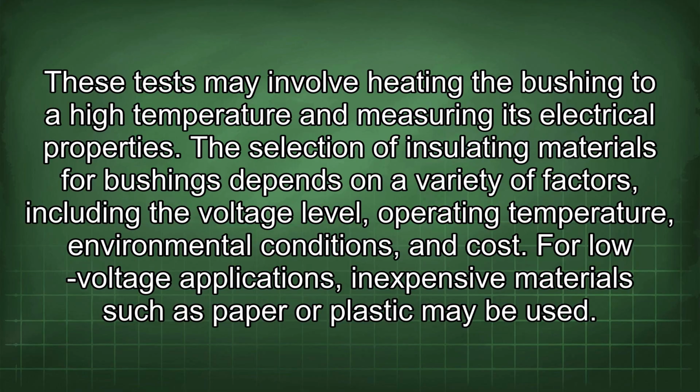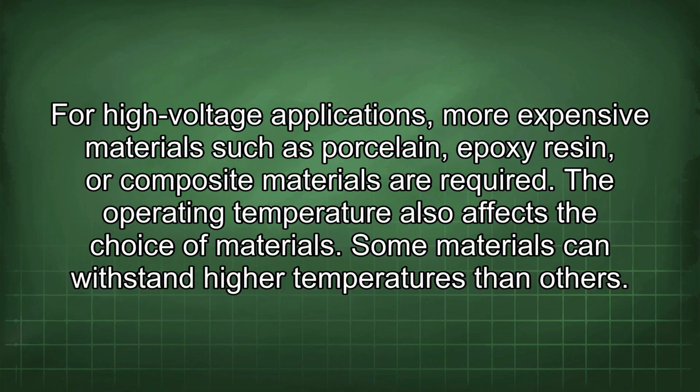The selection of insulating materials for bushings depends on a variety of factors, including the voltage level, operating temperature, environmental conditions, and costs. For low-voltage applications, inexpensive materials such as paper or plastic may be used. For high-voltage applications, more expensive materials such as porcelain, epoxy resin, or composite materials are required.